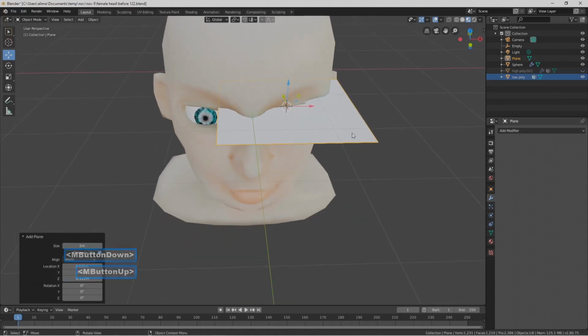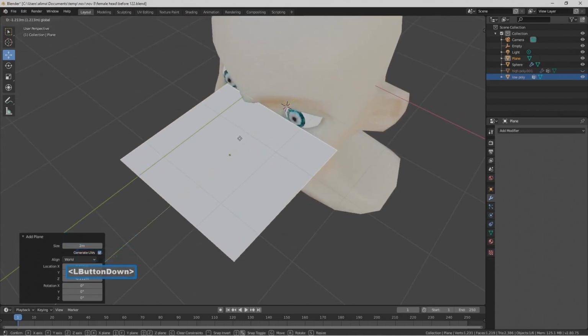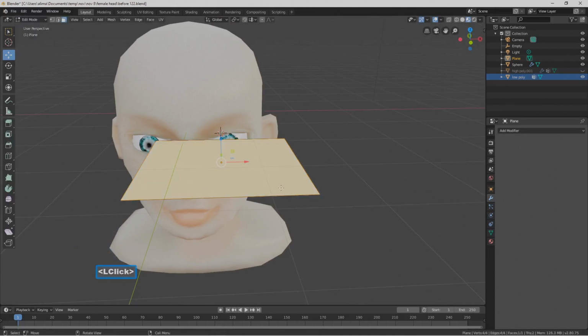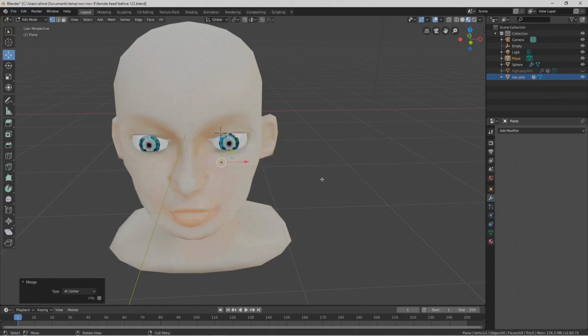With the plane here, we're going to push this plane forward. We're then going to go to the upper left, go to edit mode. We're going to go to vertex select. We're going to hold Alt, press M, which brings up our merge menu. We're then going to select At Center to merge all of that geometry together so that it's now one vertex.